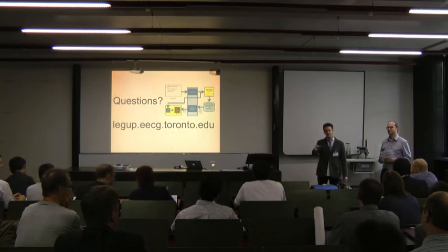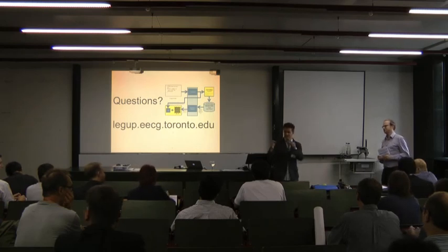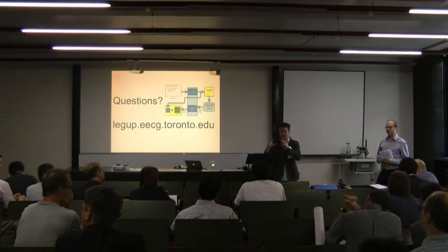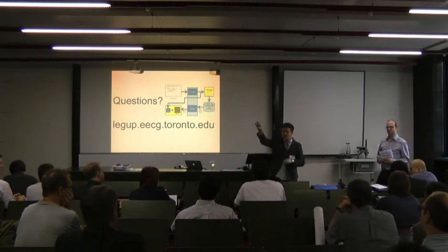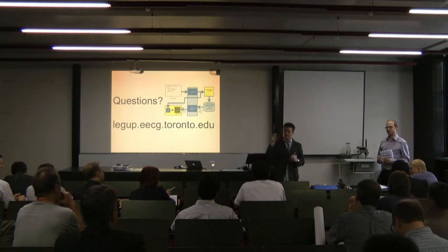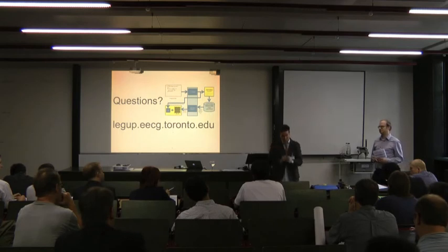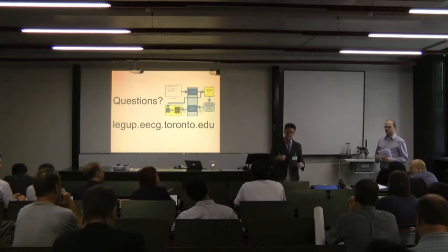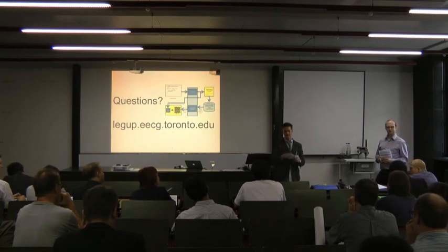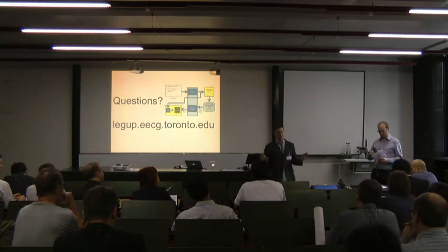But I think where you're going is this: imagine in a C function, I declare an array and I take that function and put it as an accelerator. If we can reason that the array is only accessed in that function, then we can keep the memory in that Verilog module. We don't need to make it accessible to all Verilog modules, so we do that. But for chunks of memory that we can't reason are only accessed locally, we have to put those outside, and all accesses to those go through a memory controller, which will resolve the addresses to steer the memory request to the right block. So it doesn't have to be regular memory access, completely fine.